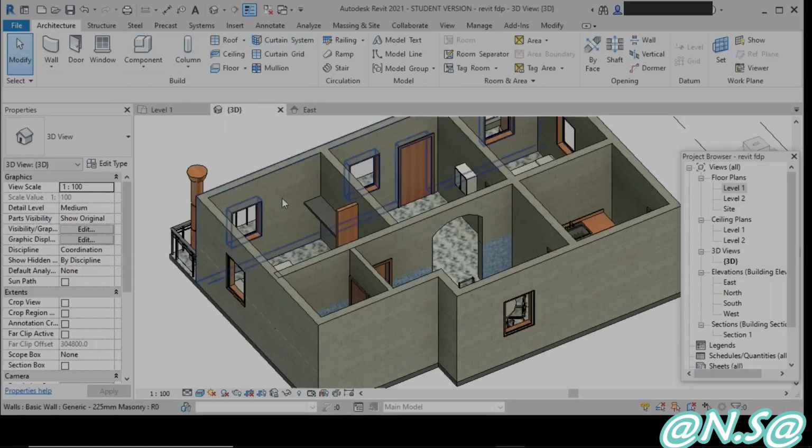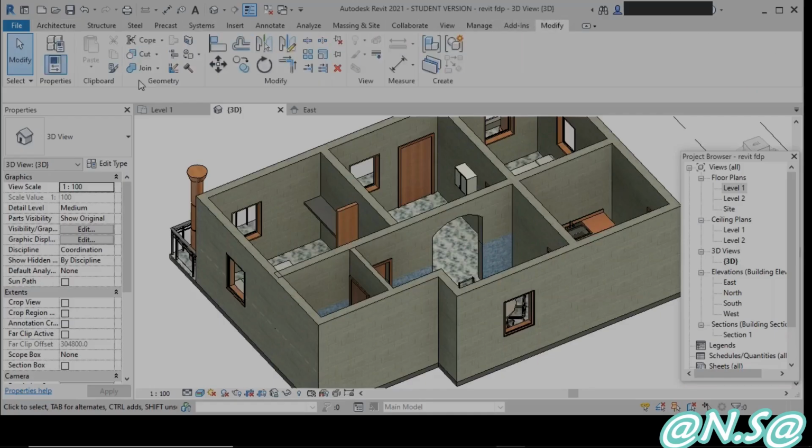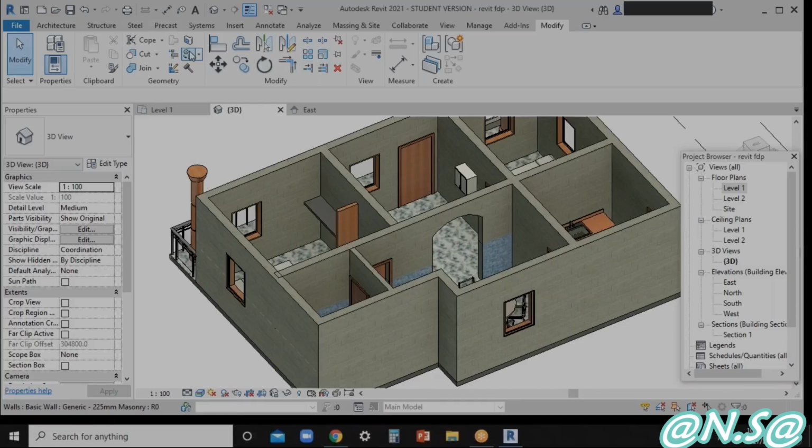Sorry, these railings have been done. As I have come to this point, let me explain the Paint option as well. We can use this Paint option in Modify in multiple ways: to assign paint for any face, or to assign a certain layer to any face. To assign the material to the face of walls or any components, we can make use of this Paint option.